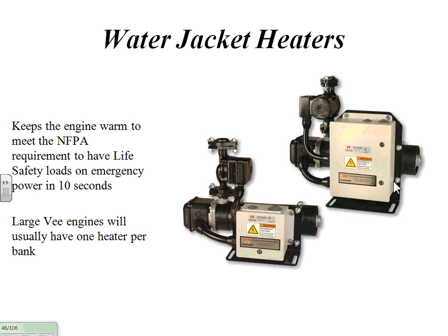To do that, we put a water jacket heater on the unit, but we also typically will, especially in our area, put in insulation, foam, and motorized louvers, all designed to what? Keep the heat in the enclosure while it's not running. So the insulation in the enclosure is important. Water jacket heaters are important, all leading to that 10-second start and supplying load capability.